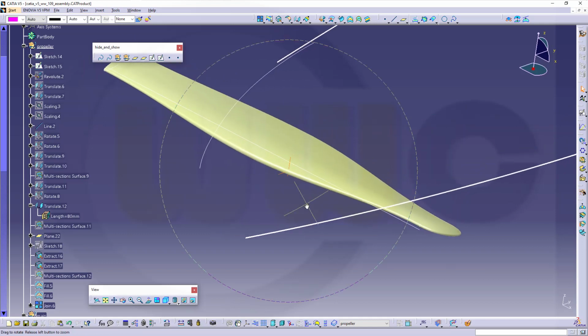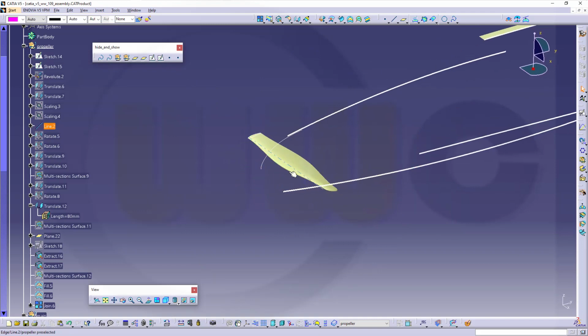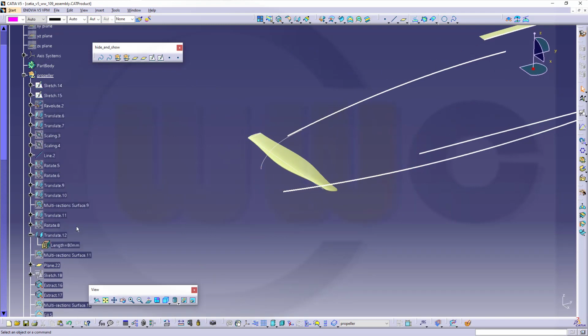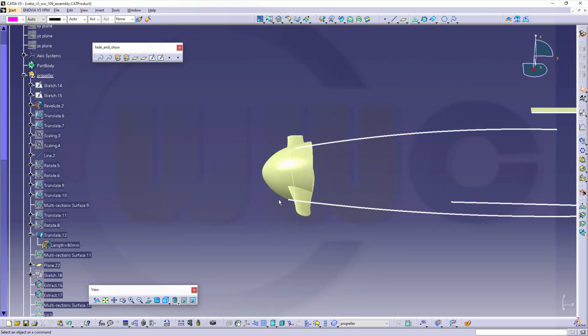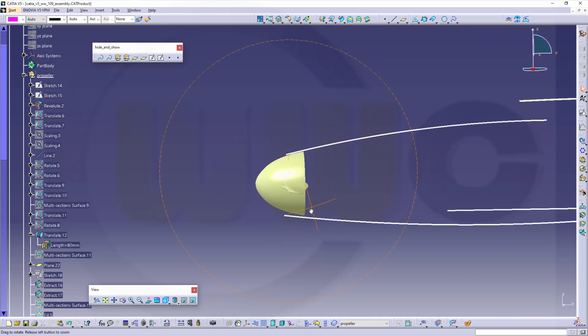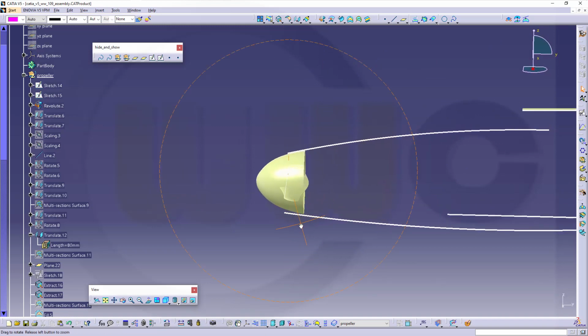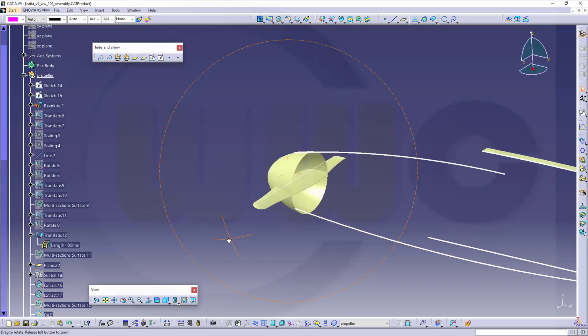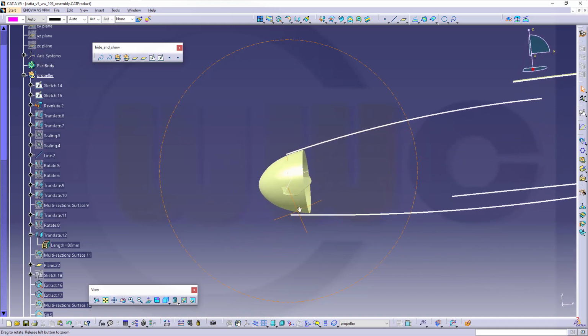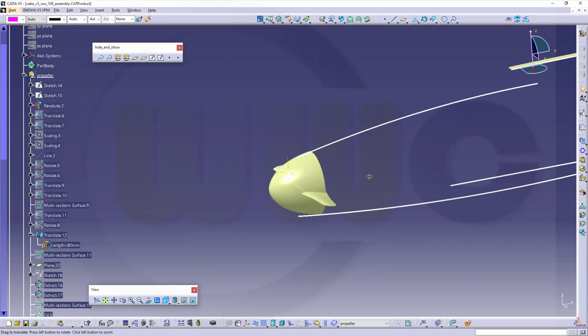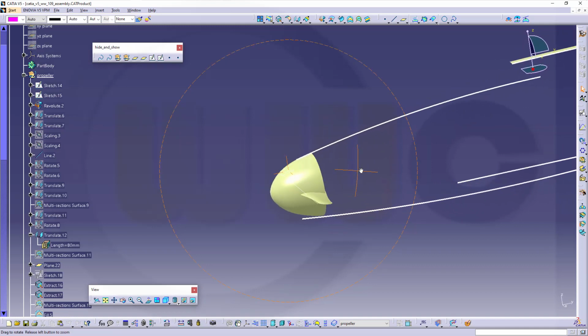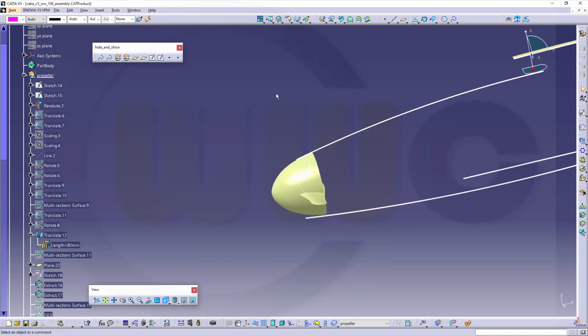Yeah. Okay, now I have to position that one in relation to that Revolut. I can move it in that direction, maybe 750, and I want to rotate it around maybe that axis by 90 degrees. Or I could go for another. Yeah, let's see how we can turn this. So first let's rotate this one by 90 degrees, plus or minus, doesn't really matter.